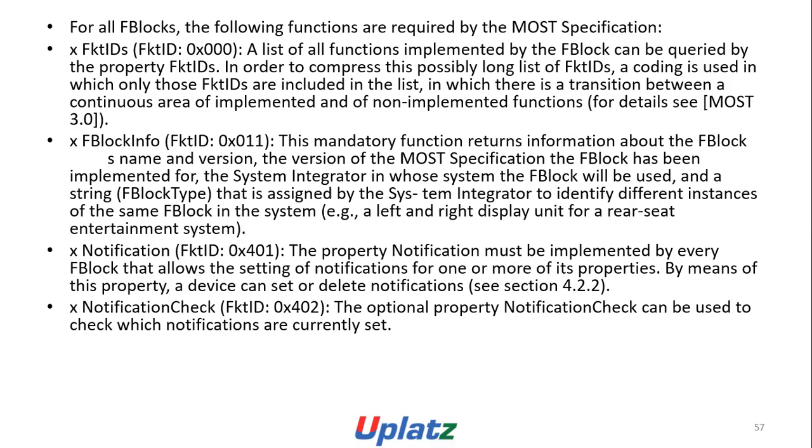Notification, FktID 0x401: the property Notification must be implemented by every FBlock that allows setting of notification for one or more of its properties. By means of this property, a device can set or delete notifications. NotificationCheck, FktID 0x402: the optional property NotificationCheck can be used to check which notifications are currently set.